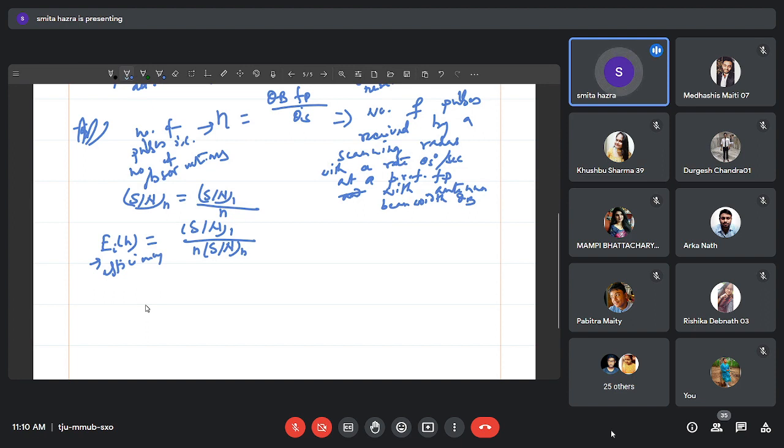And we can also measure the corresponding loss, because when we introduce some device there, the loss of that device will also be included in the total factor. So the loss of the device we can also obtain by taking the reverse of this. I have shown you the gain of a lossy device, how we performed it: 10 log 10 base of 1 by attenuation.